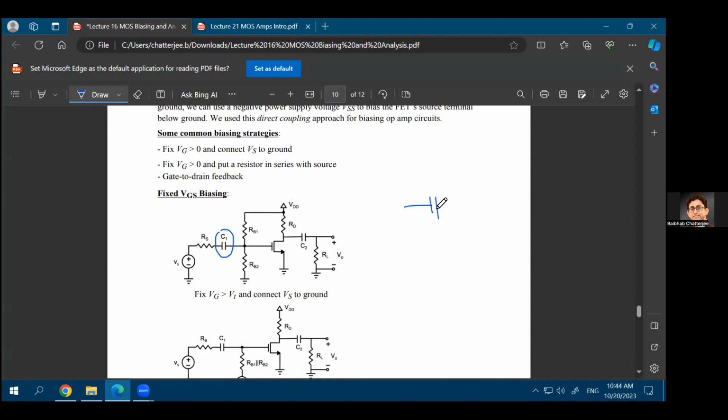So remember that this is a high-pass filter, a capacitor in series, and a resistance in parallel to ground. That forms a high-pass filter, and the pole frequency of that high-pass filter, if you plot the frequency on the x-axis and let's say transfer function or gain on the y-axis, it would look something like this, right? At high frequencies, we will get the signal. At lower frequencies, in fact, at 0 frequency, you will not get any kind of signal. So it's your job as a designer to determine this pole frequency in a way that your intended frequency is, let's say, somewhere over here, so that you do not get any loss because of the filtering action.